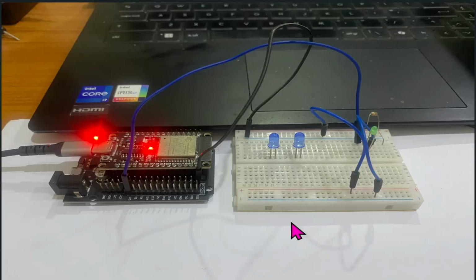So when we are sourcing current, what we are doing is we're taking the DuPont connector from the S line out to the positive side of our LED. We then go through a resistor, then into ground. However, when we are sinking, instead of taking the 3.3 volts from the GPIO pin, we take it from an external 3.3 volts and then we return it to the GPIO pin to then allow us to control the on and off state using our software that way.